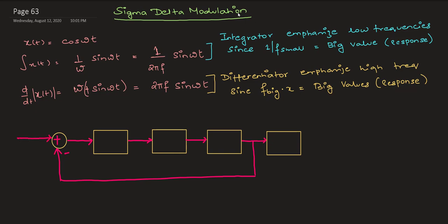In quantization you have your staircase waveform, and for the staircase waveform to become a sinusoid you use an LPF. So now the question is, what if I use the same LPF at the encoder and decoder? You use an LPF at the decoder but not at the encoder. Your encoder was deprived of a low pass filter or an integrator in delta modulation.